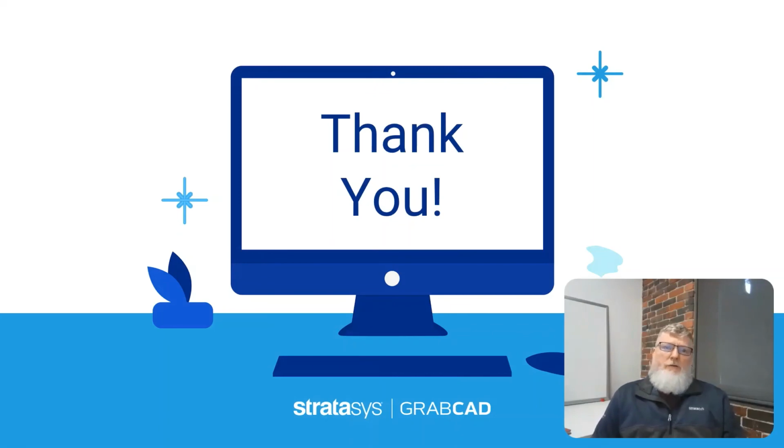We've reached the end of our tutorial, so let's recap what we've learned. When to use anchors, how to add anchors, cylindrical versus conical anchors, creating sets of anchors, removing anchors, moving an anchor to a new location, editing or deleting existing anchor features, and what you can do and cannot do to models with anchors. Now it's time for you to take this information and use it on your models that need anchors.